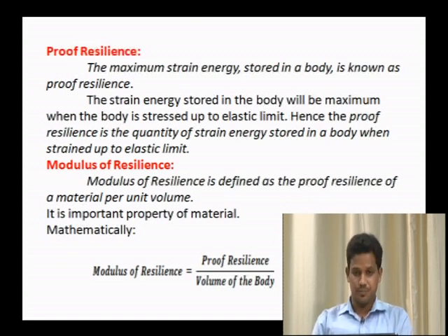When we are calculating the strain energy, as I already told, this should be within an elastic limit. Another important technical term here is modulus of resilience. What is the meaning of modulus of resilience? We are calculating strain energy or proof resilience per unit volume.